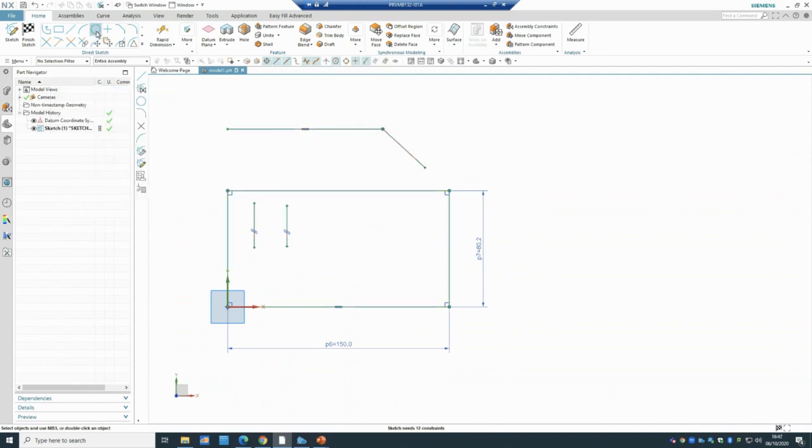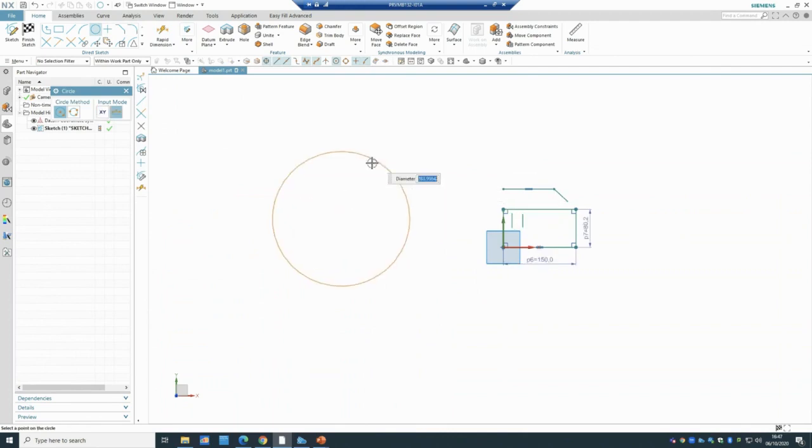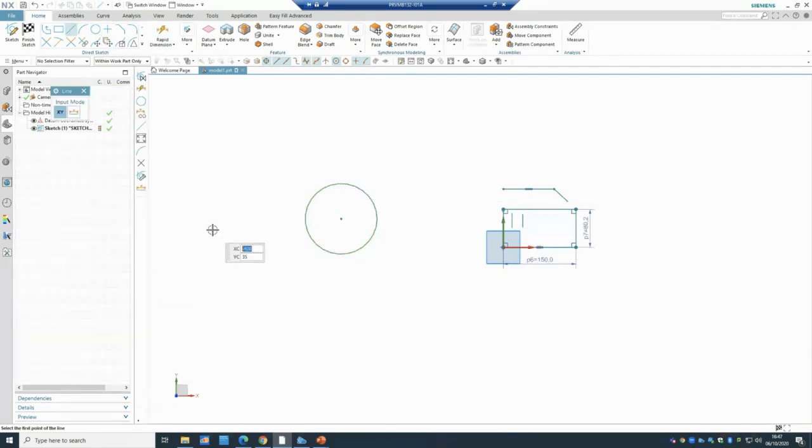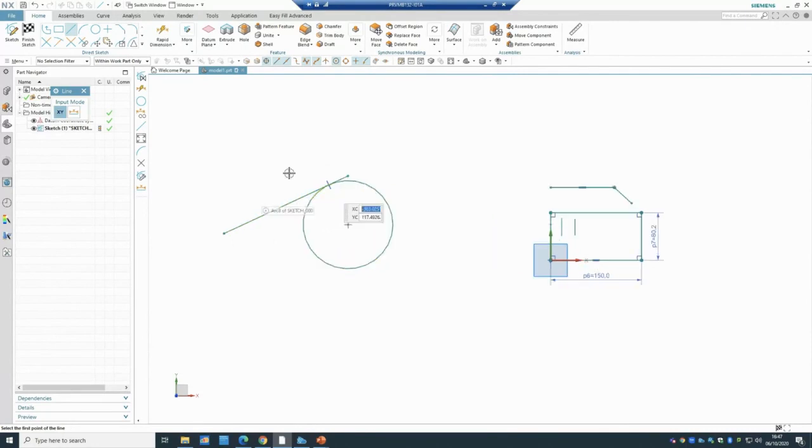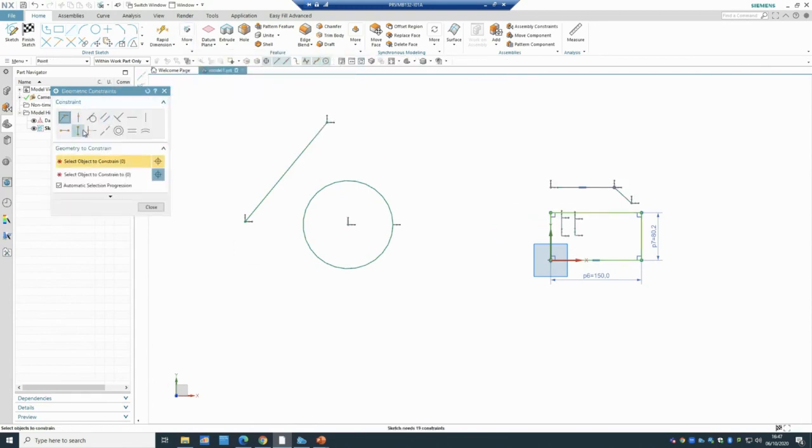The other thing, let's make a circle. Whenever I want to draw a line, because I have activated the automatic constraint, whenever I get near the circle, do you see that sign appear? That sign means tangent, so it becomes tangent. We use it a lot. So you can either just rely on that, and that sign means they meet each other and also they're tangent, or if I do Control Z, let me draw a line, and then I can come back with the geometry constraint, and tell the software I want the circle and that line to be tangent with each other, for instance.